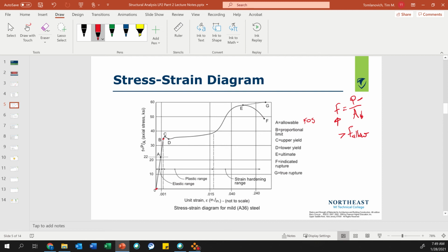And then if you remember, the horizontal steel beam that's holding up the highway was actually deflecting. However, due to this situation, that deflection stayed in the elastic limit. So that's why they didn't have to tear the bridge deck apart. It stayed in the elastic limit, so when they jacked it back up, it went back straight. We did not have any permanent deformation. They did some calculations showing we're still in the elastic range. So it's a very interesting phenomenon.